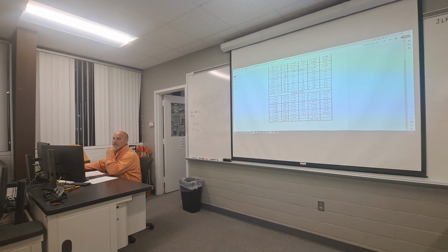When you come down here at the bottom, just like you see with the architectural scales, if I'm at 1 inch equals 10 feet, and I'm putting my text in that viewport and I want it to print out at 3/32 height out of that printer, I'm going to tell AutoCAD to make that text 11.25 inches tall.